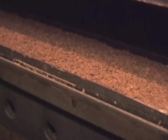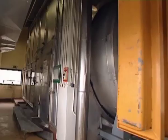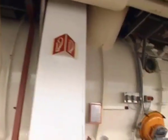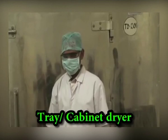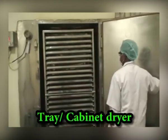Drying can take place by radiation in equipment such as infrared, microwave or radio frequency dryers. It may be noted that industrial dryers can be operated as batch or continuous type. Commonly used industrial dryers include tray or cabinet dryer, drum dryers, fluidized bed dryers, tunnel dryers, vibrofluid bed dryers and state-of-the-art field assisted dryers. Tray or cabinet dryer is the least expensive, that is why it is the most common and popular dryer.